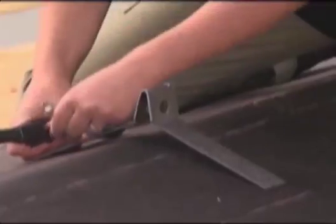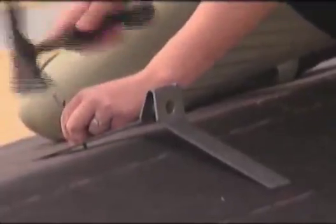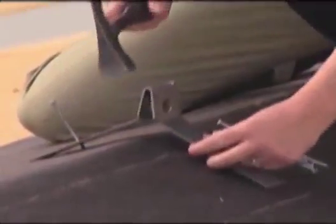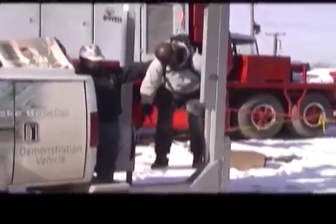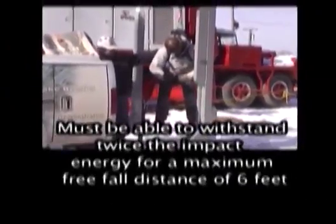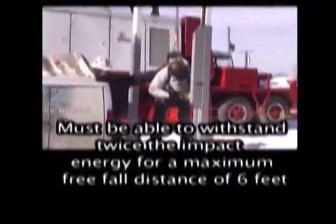One must rig the PFAS so that an employee cannot free fall more than 6 feet nor contact any lower level. An employee must come to a complete stop and limit the deceleration distance to 3.5 feet. A PFAS must have sufficient strength to withstand twice the potential impact energy of an employee free falling a maximum distance of 6 feet, or the free fall distance permitted by the system, whichever is less.